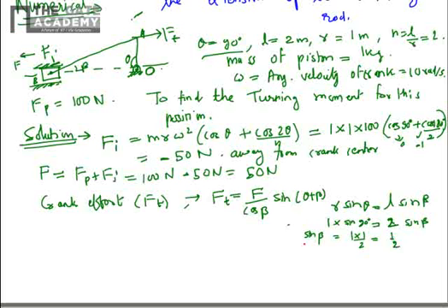If you do sine inverse of half, you get beta is equal to 30 degree. So beta is 30 degree. Now we substitute these values in the expression for Ft, that is F by cos 30 degree sine 90 plus 30 degree.